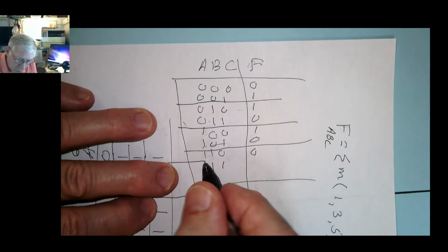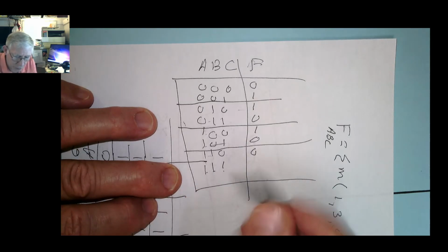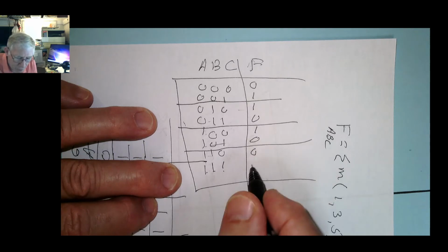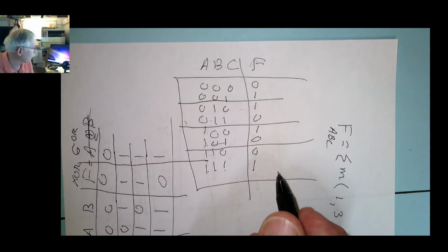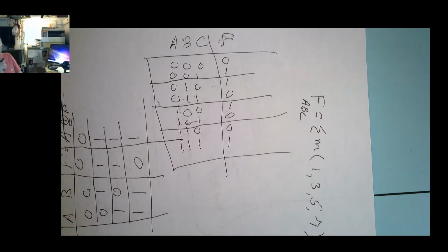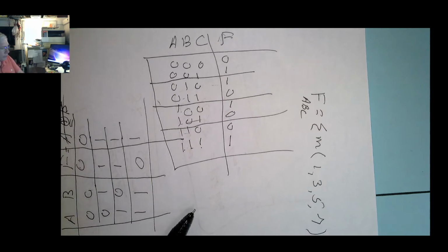What about when all the inputs are 1s? For a 3 input, it's back to a 1. Which sounds a little screwy, because it doesn't sound as exclusive as an exclusive OR gate. But that's how it's defined, so you just have to sort of memorize that. It's more like an even or odd gate, but there is such a thing as an even and odd gate, so I'm confused about that.